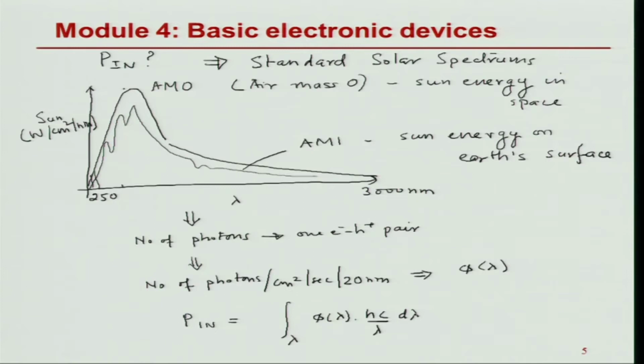So, what we are characterizing in a solar cell is how much power I am collecting from the solar cell, and how much total sun power I am able to collect per unit area at that point. If I take that number, that is the efficiency. This is the number that we quote again and again when we describe our solar cell. Keep in mind, whenever we quote this number, we must also quote the standard spectrum we are using for doing this measurement. Now, what are these numbers generally like?